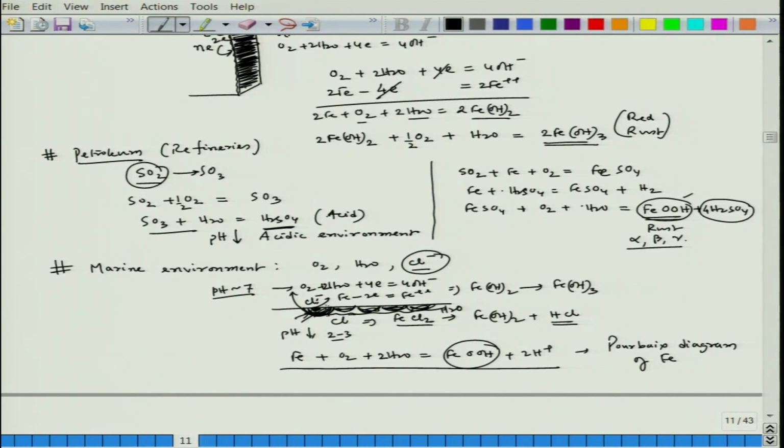Initially it starts with this particular corrosion product, the way it has been explained, and once the chloride ion is present, it will react with Fe and form FeCl2. It will hydrolyze and then form Fe(OH)2, and finally it will keep on corroding in these sections, and if this distributes over the entire surface, then you can have a uniform corrosion mode.